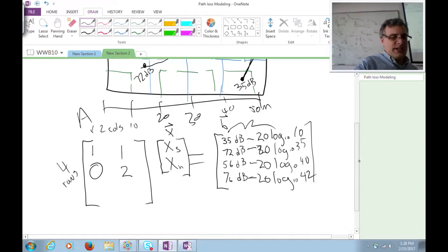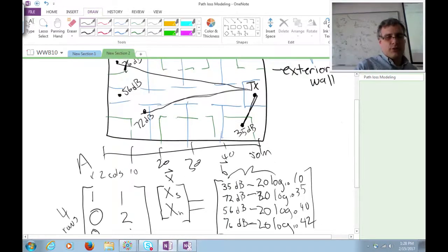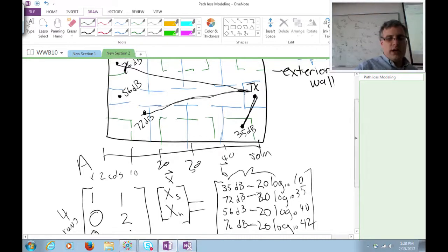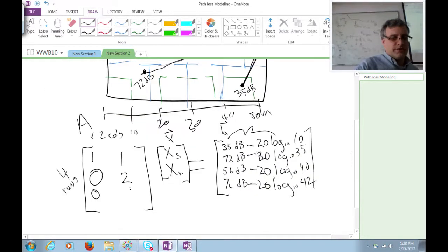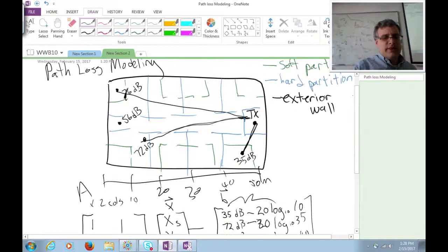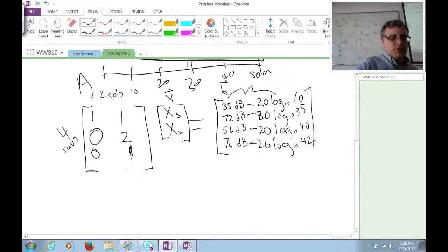Man, that one goes straight down the hallway. I'm just going to put 0 here. Oh, wait. No, wait. I go through this one, don't I? Yeah, I do, 1. Do I call that a hard or a soft? Hard. Otherwise, straight down the hallway. And then this guy over here, I go 1, 2, 3, 4. Oh my, he's going to be really lossy. It looks like it goes through a soft partition too. I'm going to put 1 soft and 4 hard. And not surprisingly, he's the lossiest point there, so that's consistent with the physics that's going on.